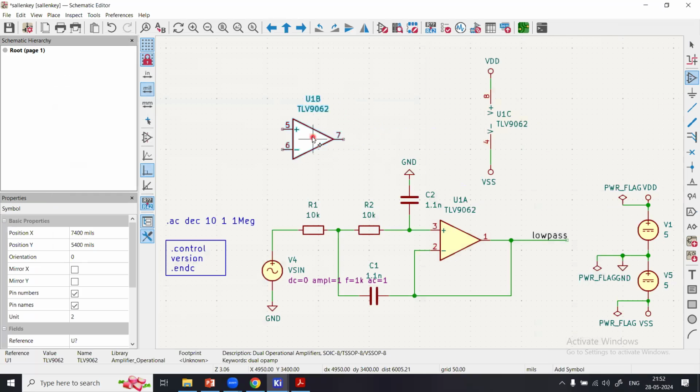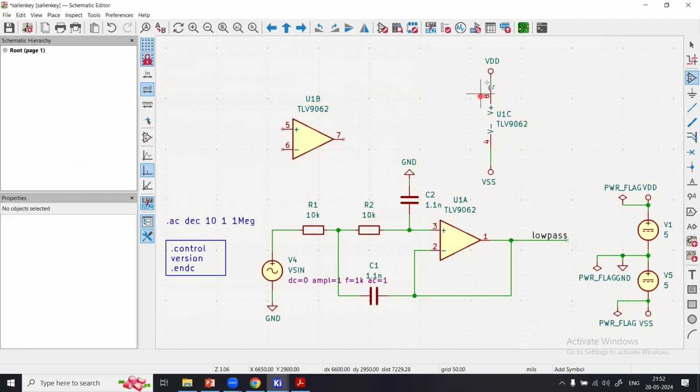And if I place this component right here, then press escape, because this part is reflected now and it has to be placed here. So I have used all of them: U1A I have used, U1B I have used, and U1C I have used. So the full IC I have used. But since for this specific explanation I don't need this part, I will just delete it. I will keep these 2 parts, U1A and U1C. And after that, I have done these connections.